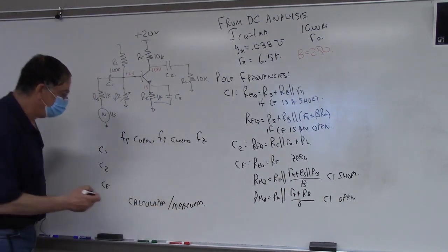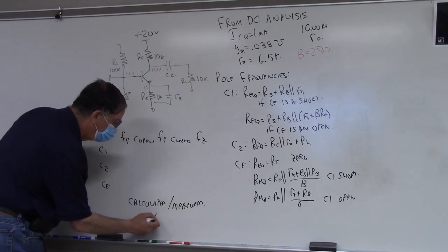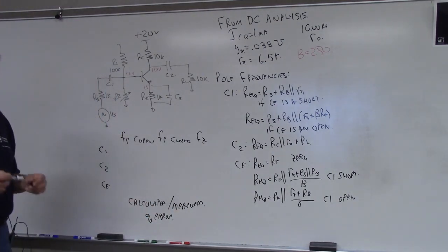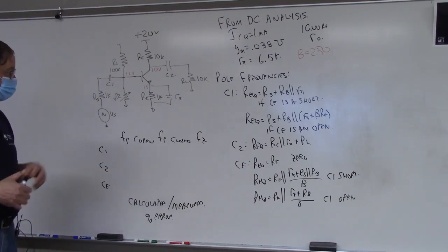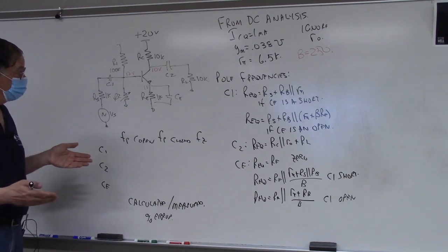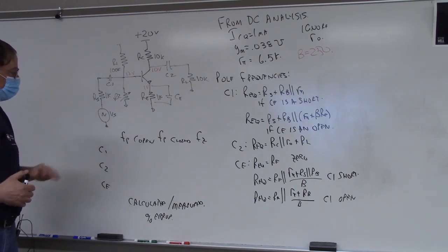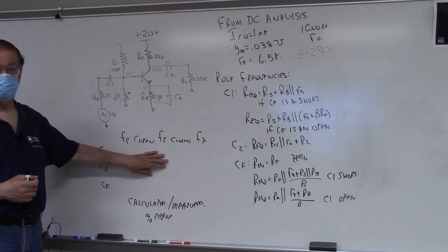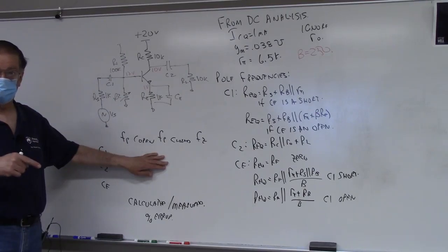It would also be nice to give a % error between these two to see how close we got it. As far as sources of error go, there are quite a few. Our beta could be off because we're dealing with different transistors. Also, as we'll see with the oscilloscopes, slow moving waves are difficult to measure on an oscilloscope because the oscilloscope itself doesn't like to trigger on slow moving waves.